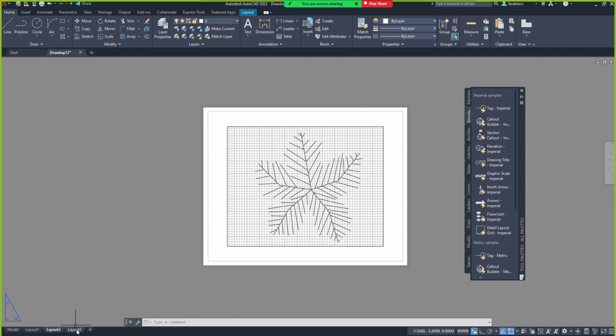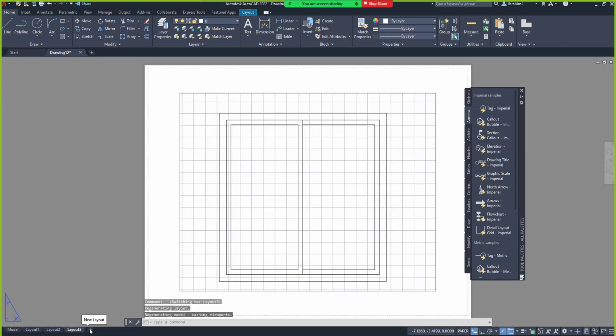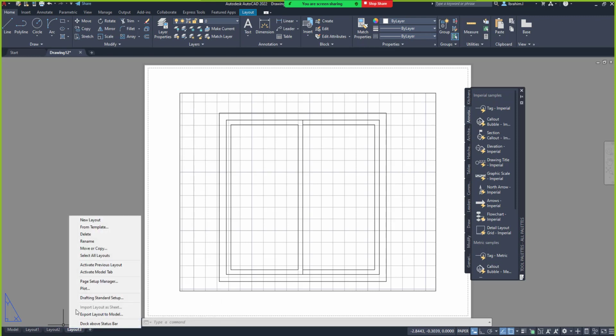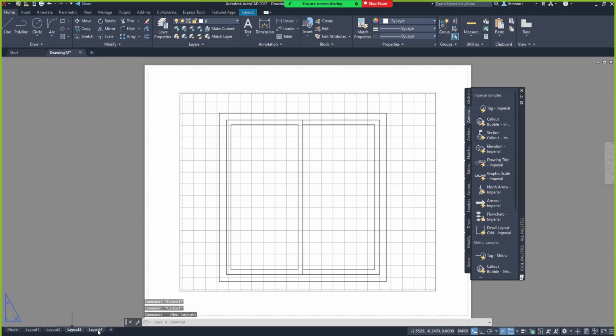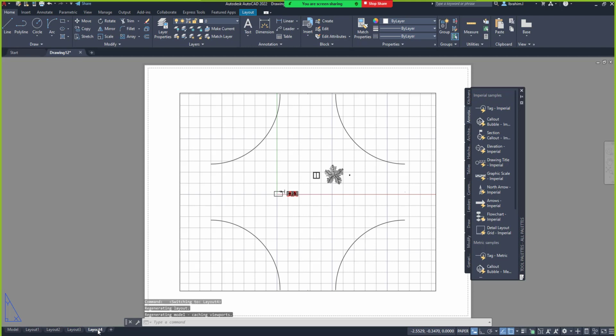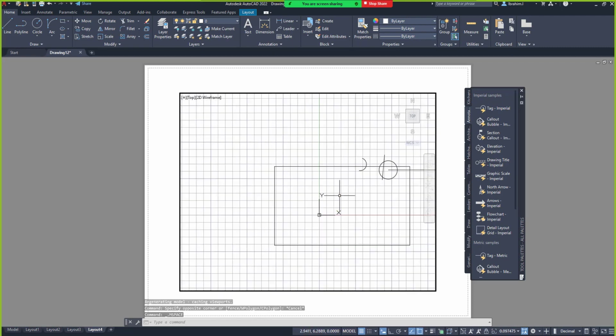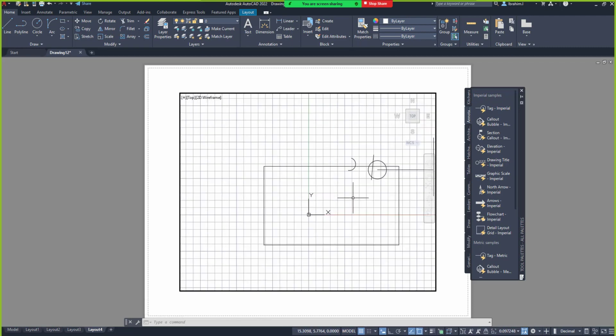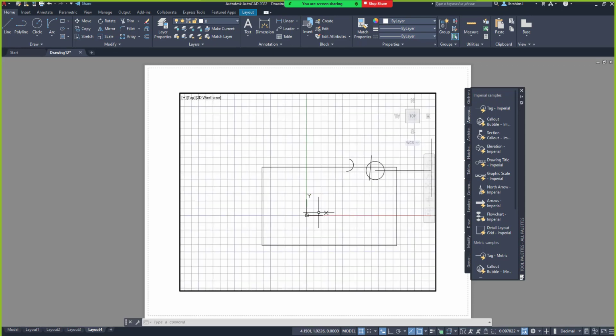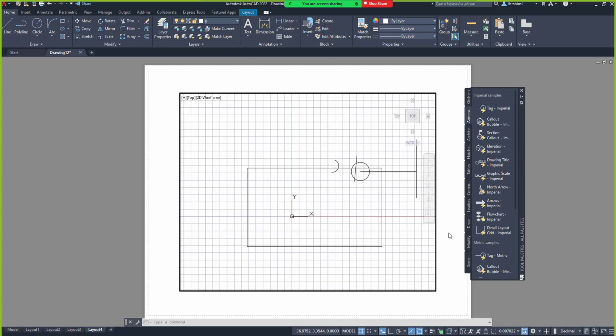Now, all these new tabs, the layouts that we created using this plus icon, there's another method to create a layout again. You can also right click on one of the layouts and then go to New layout. Can you see that? It will also create a new layout for you to start adjusting. By default, immediately you click on create new layout, it won't take from any other design. It will go back to the default view of everything that you have on your workspace. It will want you to adjust to whatever you want to see, or what you want to have printed. That's what you adjust to here. And immediately you have it on view, all you need to do is click out.